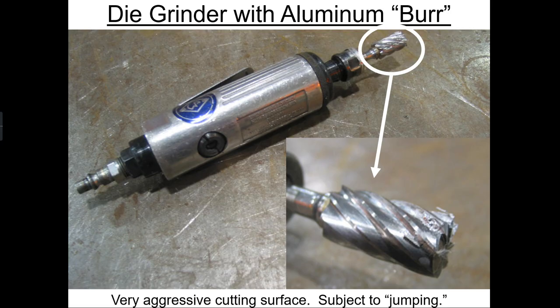Aluminum's too soft. Materials get buried in it and they will cause porosity throughout the weld. Any type of abrasives are going to give us nothing but trouble. The abrasives have little bits of glue on them for being attached, or the resin gets in there from the closed coat type of buffing pads, and they will, when hot, cause us all kinds of problems.